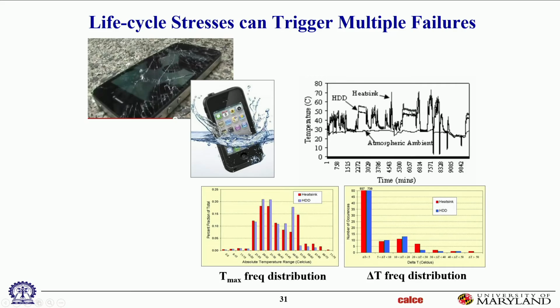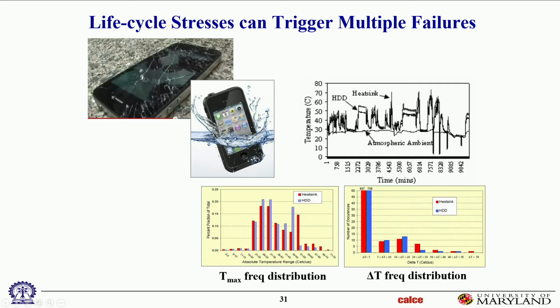So wear-out mechanisms are like cumulative damage. Every day it has to survive this temperature environment, and it has to survive 3 years of that. So it's a cumulative wear-out damage, hence the term wear-out. And these are overstress events. The failure happens when that event happens. So the idea is never to let your product get exposed to such a severe overstress event. But if it happens, the product dies right there. Whereas here it has to survive 3 years or 5 years of this environment.